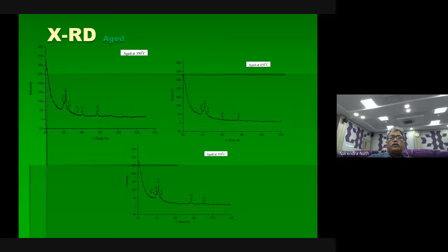And if you do the same thing after 800, then 350, 450 and 550, the low temperature retreatment, B2 is there, B19 is there, and the remaining precipitates come into the picture. If you want to do quantitative analysis in terms of percentage, it is not possible with normal XRD. Then you have to go for high-end XRD, which will tell you what the percentage of each is, and whether it increases or decreases with respect to your previous graphs.